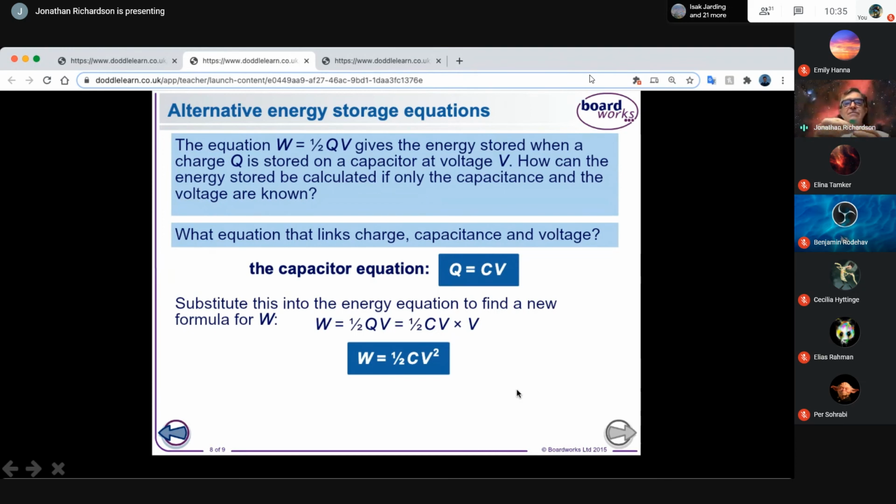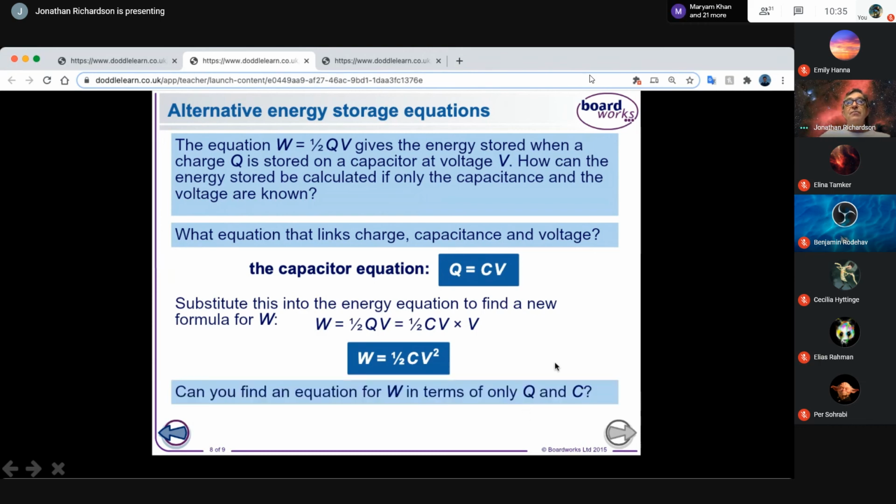You can take a meter and measure the capacitance, put the terminals on here, measure the capacitance. It's actually written on the top of it, so you can tell this is a 1 microfarad capacitor. And we can measure the voltage using a voltmeter across here. We know the capacitance and we know the voltage, we can work out the charge.